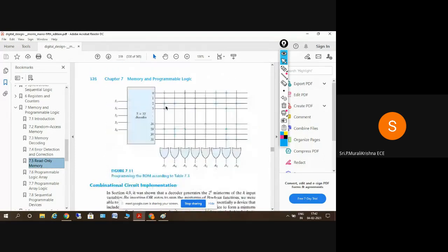Okay, so earlier what will be done here is, the manufacturer, in the case of the PROM, will put all cross marks here. I mean fuses will be generated for all the things here. Initially there are all ones, I mean, initially there'll be all contacts from the decoder to the OR gates. So, getting my point here?